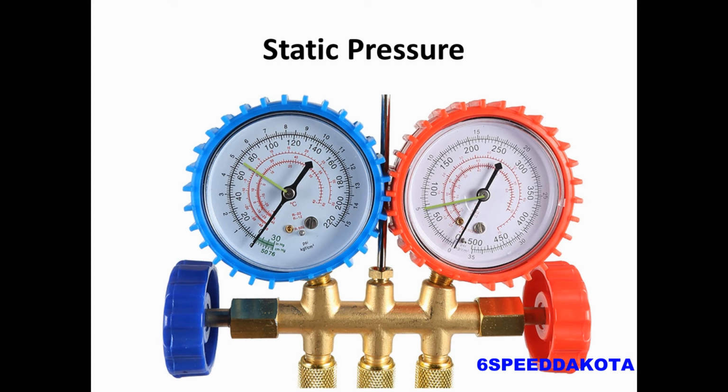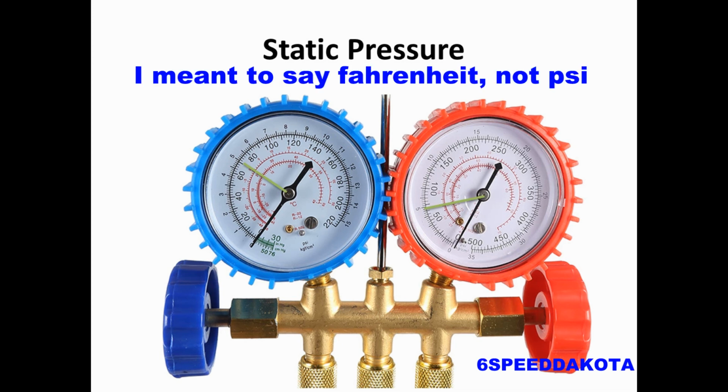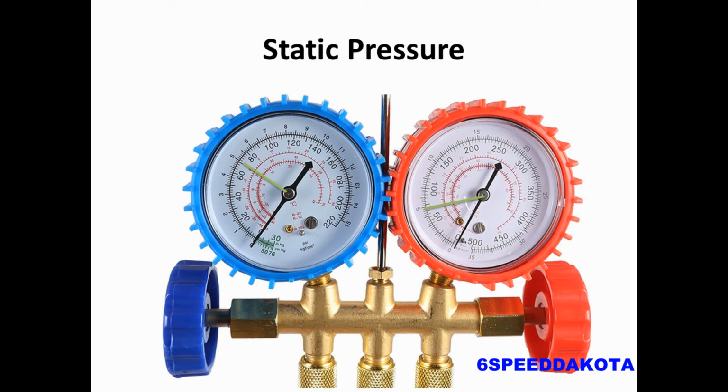But if you're doing R134A, you need to have a gauge that reads for 134A. This will still read the pressures, but your condenser and evaporator core temperatures are not going to be correct. So with R134A, generally your static pressure is very, very close to what the ambient temperature is in Fahrenheit. So if we're going from 70 degrees, both gauges should read approximately 70 psi.